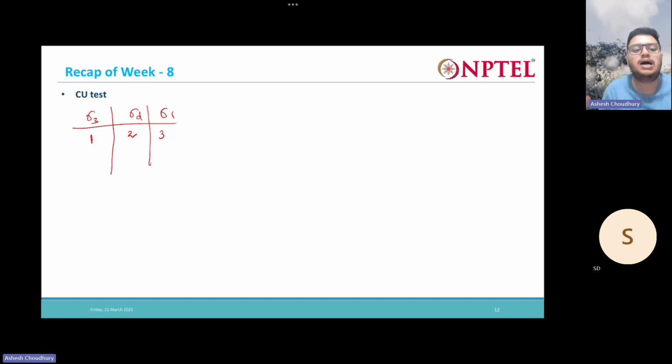Next, you increase the sigma 3. Again you allow the soil to consolidate completely at that sigma 3 value, and then you again start increasing the sigma 3. So now sigma 3 is 3. Now you will see sigma d has maybe increased to 7, because as you increase the confining, the consolidating effective stress, the consolidation is happening.